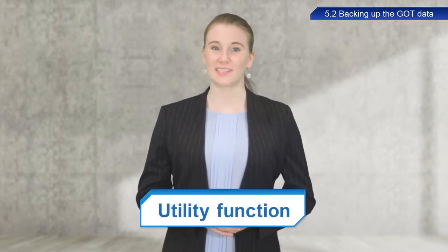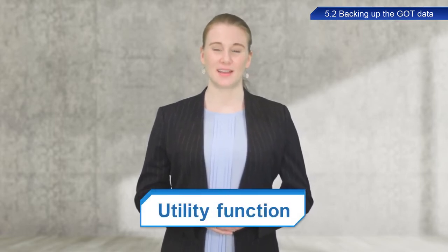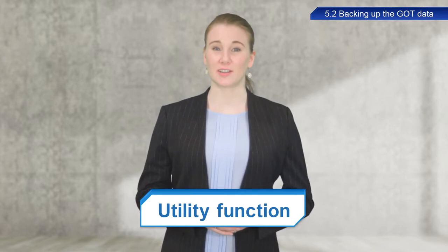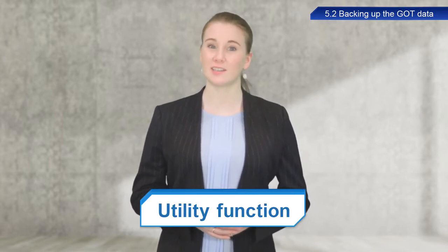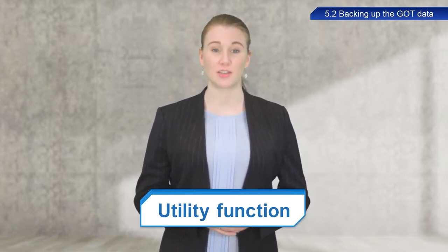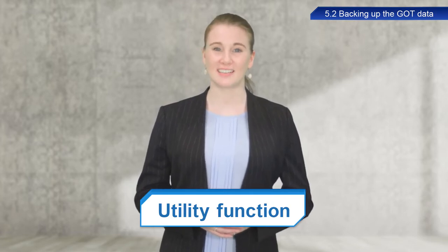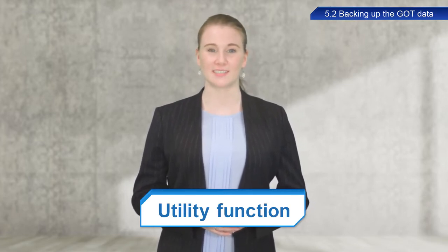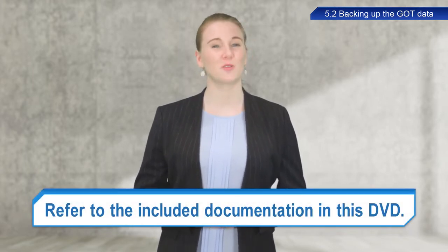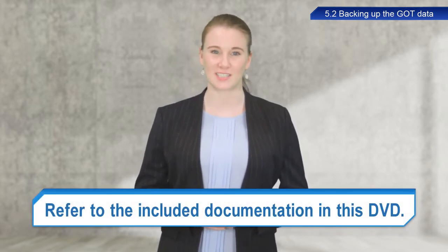Backups are performed using the utility function. Utilities are used to configure connections between GOTs and other devices, configure screen displays, manage data, and perform other functions. A note of caution here. Before you can execute the backup utility, the backup and restore extension must be installed in the GOT's built-in flash memory. Refer to the included documentation for more information on the installation procedure.